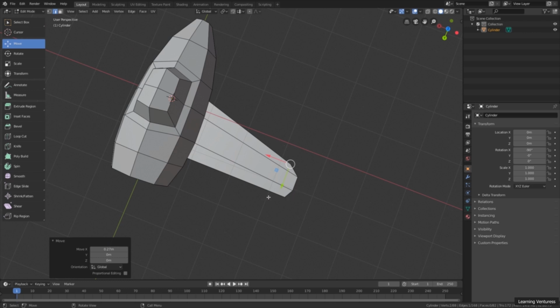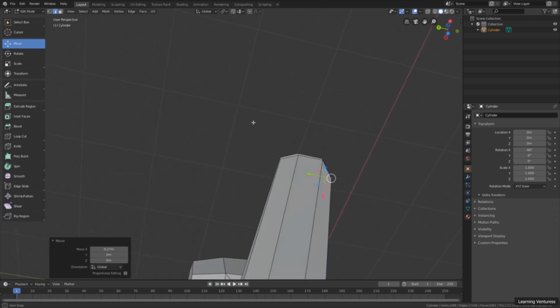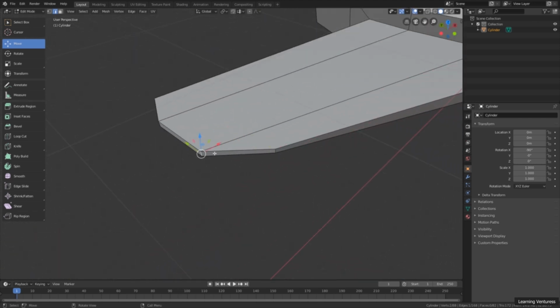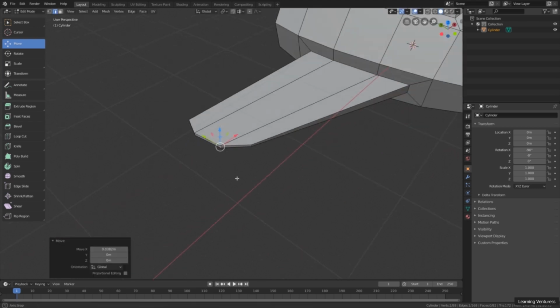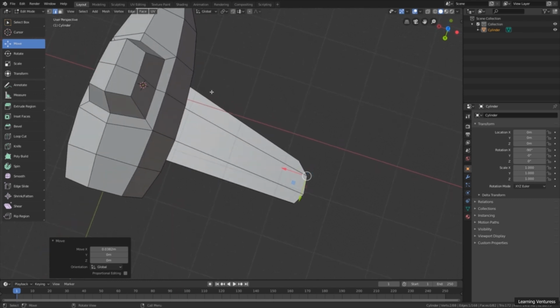And now, so that we can make the center part of the wing also a bit round, here in the back part, I need to create some segments in the middle of the wing. Okay, and for this I'm going to use the Loop Cut tool. Let me finish some adjustments here. Okay, but now I'm going to use the Loop Cut tool and create some segments in the middle of the wing so that I can adjust the edges and make this shape look round like this.